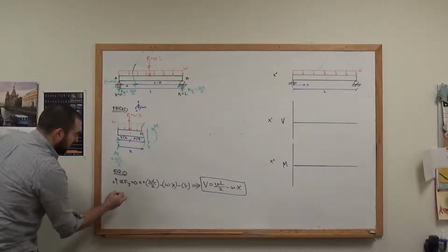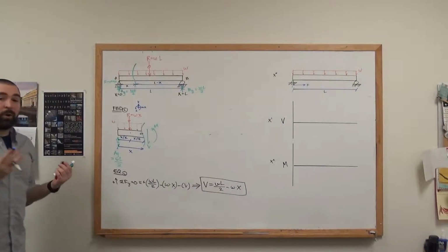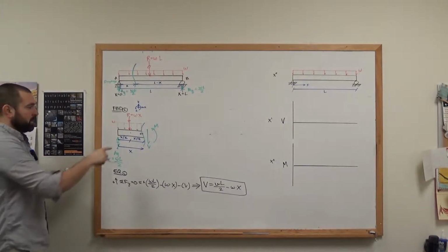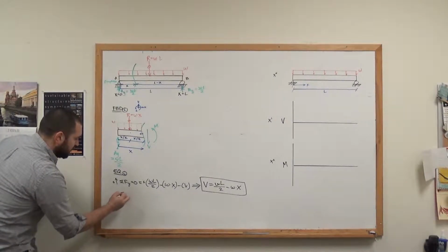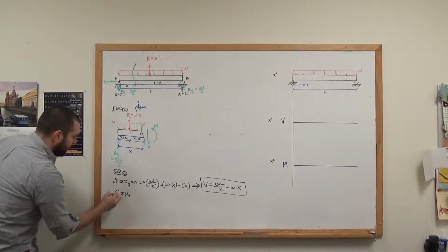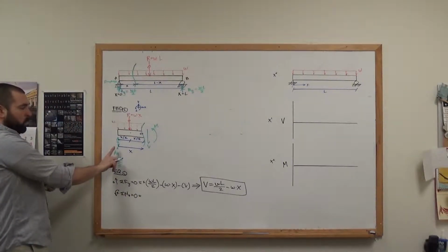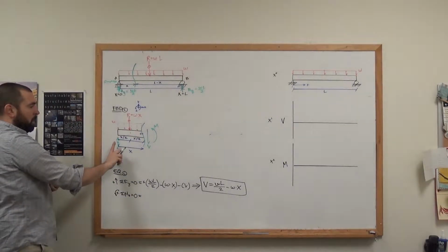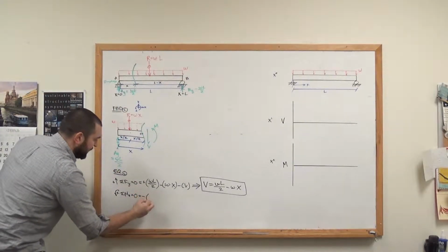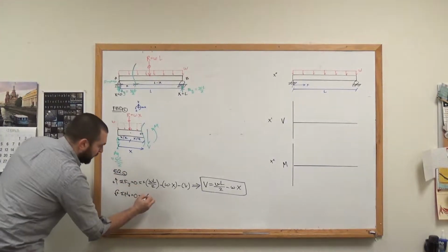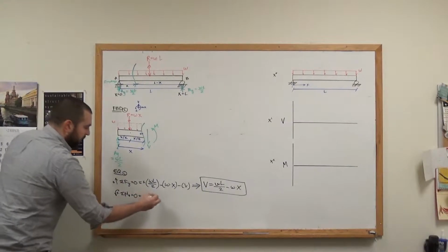Now here, if I want to find the internal moment M, the best place to sum the moments about, not the only place, but I think the most efficient place, is the section cut itself that I often call point O. So if we sum the moments about the section cut equal to 0, well, AY here certainly causes a moment about O. It's a clockwise moment about O, so it's minus. The force component is WL over 2, and the distance component is X.